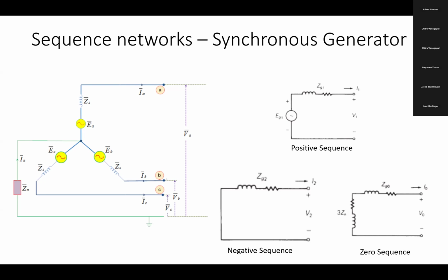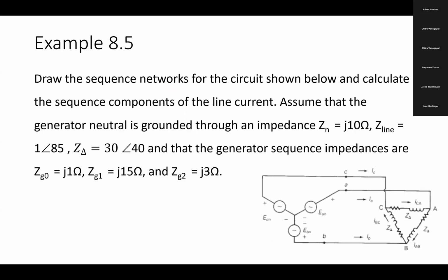Okay, so let's look at how to connect the transformers. What are the thumb rules for transformers and different types? Before we go into that, let's do one analysis. We know how to draw the sequence components for the load. Now let's connect it with the source. We are not looking at the transmission line here. Ignore the transmission line. Just look at the source and the load. Now we are putting two systems together, the simplest system, and let's try to draw the sequence components for this.